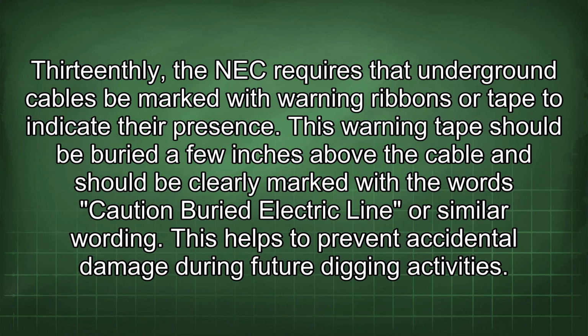Thirteenthly, the NEC requires that underground cables be marked with warning ribbons or tape to indicate their presence. This warning tape should be buried a few inches above the cable and should be clearly marked with the words "Caution buried electric line" or similar wording. This helps to prevent accidental damage during future digging activities.